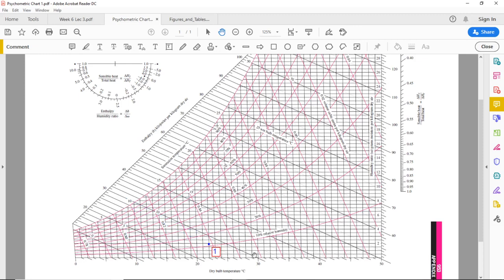And the humidity ratio, you can see we are just under 2 grams per kilogram dry air, so that was 1.9 gram per kilogram dry air, and the constant specific enthalpy lines we can draw any one from over here. And if I just take it to the desired state point, you can see this is 20, 22, 24, 26, and this is 27 kilojoules per kilogram dry air. So those values we have now confirmed,